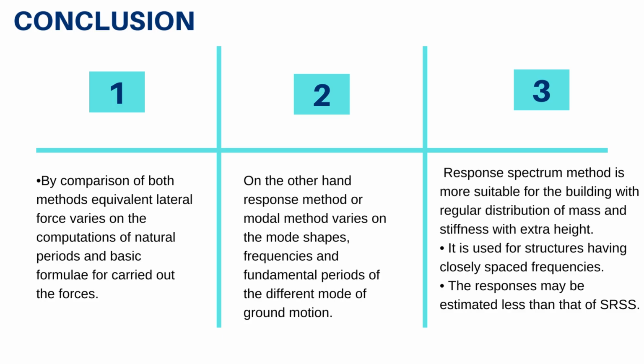Conclusion. Comparing the two methods. Equivalent lateral force method: the lateral force varies based on natural periods and basic formulas for force calculations. Response spectrum method: the lateral force varies based on mode shapes, frequencies, and fundamental periods of different ground motion modes.